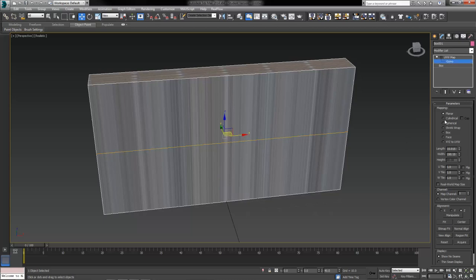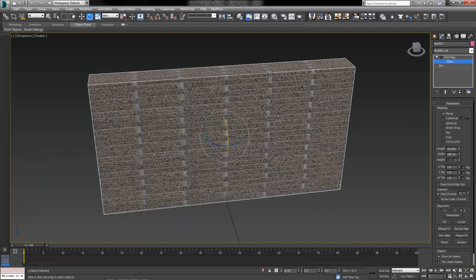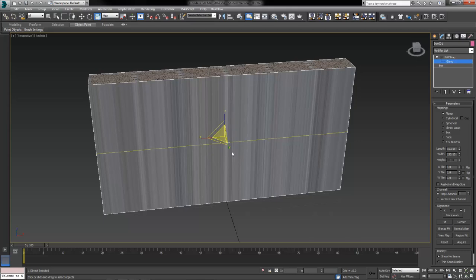You can click to highlight this Gizmo blue, and then when you use your move, rotate, or scale tools from here on out, it's not going to have any effect on your actual 3D model, the actual object itself. What it is affecting is the projection of that picture of bricks, that texture that we have created. And we're just adjusting how that is displayed in a completely different coordinate system, right?